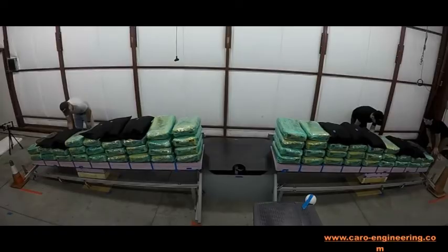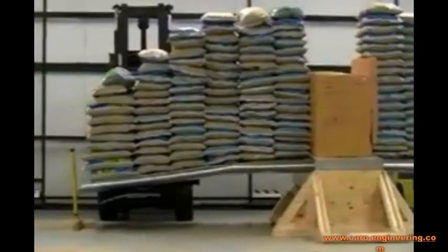To make sure the structure does not fail in flight, the primary structure is loaded in a ground test. This may be as simple as stacking sandbags on the wings. The wing here is inverted because the highest flight load is up, but gravity pulls down. A support that simulates the fuselage is used to carry the whole assembly. This works only for short wings that do not bend much under load, otherwise the weights will slide off.